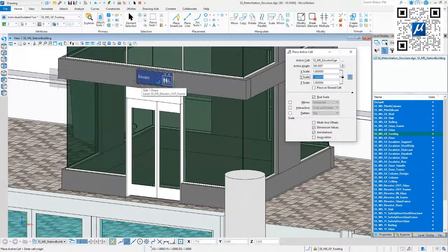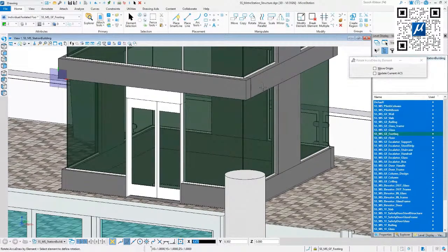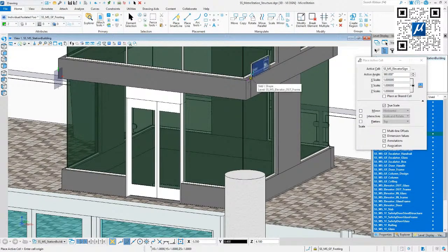And Accudraw helps me to get to these surfaces of solid elements, for example. And if I want to go to the right side here, then it wouldn't fit. So all I have to do is a little shortcut with Accudraw. It's rotate element. Then I pick the element. You can see Accudraw is rotated now. You have to accept. And that's how I get my sign to this side over here.